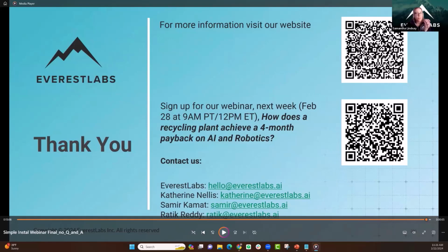And then outside of changing the suction cup that we recommend, is there any other preventative maintenance that we recommend? No, I think all of that has been covered in the video that Pratik described, where all we ask is to just clean the end effector using the bottle cleaning brush and just replace the suction cup with a new one. And we provide all those suction cups to you. So we ask that you generously replace them as and how you see fit.